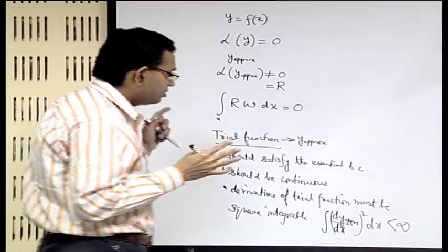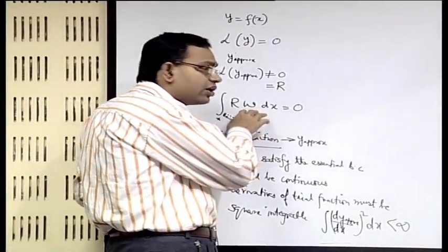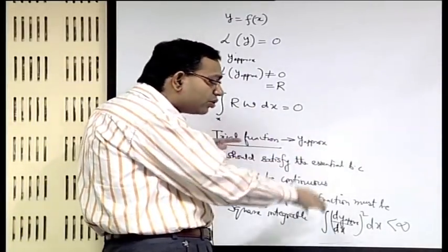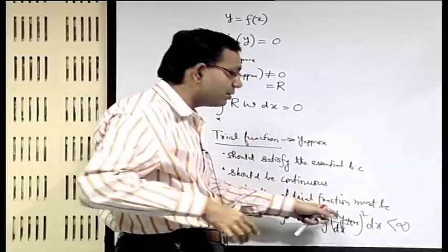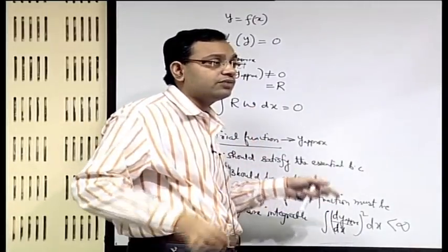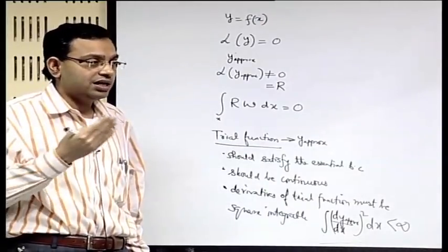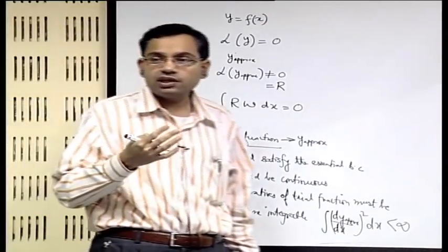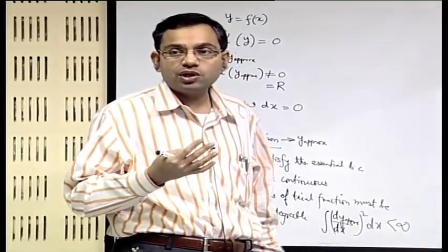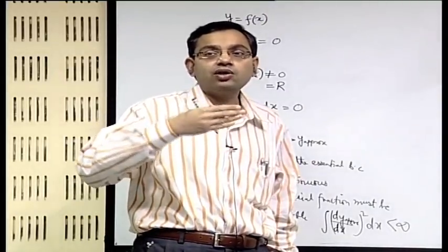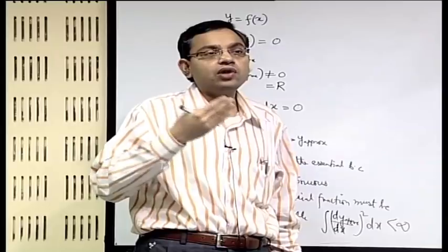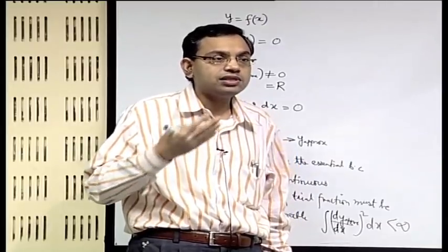But for a second order problem, if you do not go through the variational formulation, you will require a second order derivative continuity if you do not reduce the continuity requirement through integration by parts. So, the variational formulation is sometimes called weak formulation, because you weaken the requirement of the order of the continuity of the approximating function.